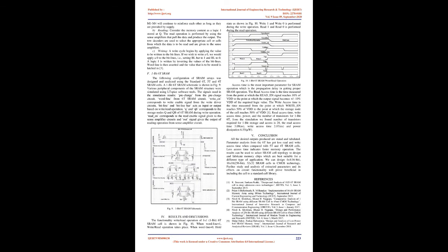Sense amplifier circuit schematic. 6T SRAM cell. The 6T SRAM cell design can be done with two back-to-back cascaded CMOS inverters, which is advantageous, i.e., this topology has good noise immunity because of its large noise margin and low static power dissipation due to less leakage current in the cell. It consists of 6 transistors, of which 2 are NMOS pass transistors for access, as shown in Fig 8. It has high speed, better noise immunity, and lesser area than other SRAM cells.